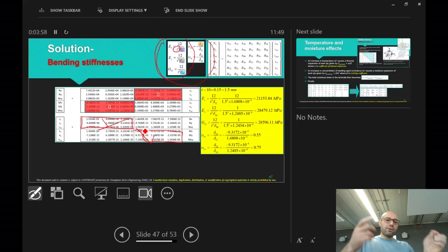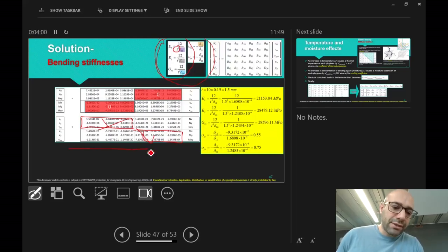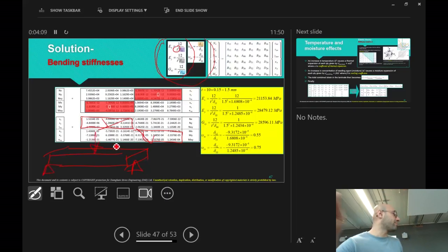If you had a composite beam like this, in a three-dimensional format, let's say a composite beam, simply supported, with a point load there, this structure is not experiencing much membrane loading, it's all in bending. So you should use EX and EY from this calculation.